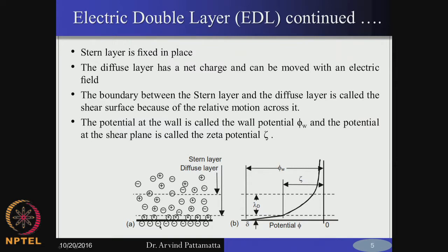So, generally, before you check whether you can actually use the phenomena of electrokinetics, people first measure the value of the zeta potential with the electrostatic part of the fluid before applying the electric field, and then they decide whether this fluid and solid combination is good enough to drive the electrokinetics by an external field. So, I think this part is pretty much clear to you.